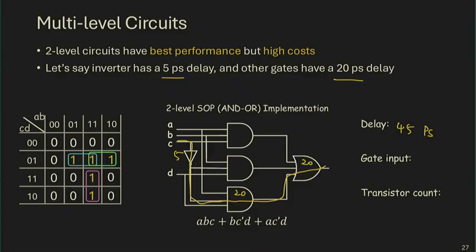So let's say you have a 1 gigahertz processor. You essentially have 1,000 picoseconds for each clock cycle. Right? If you have a 5 gigahertz processor, you have 200 picoseconds. So actually, real-life circuits are typically somewhere between 15 and 20 levels, maybe 13 to 20 levels. That's a pretty accurate number for real-life circuits.